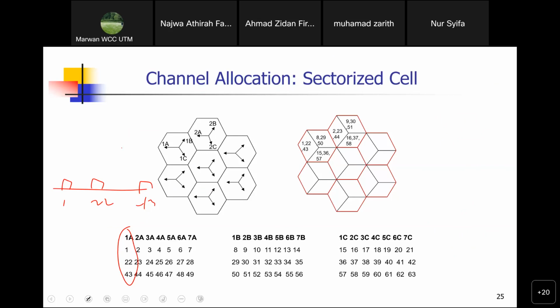If your local oscillator frequency is slightly changed, when you multiply it with the signal, your IF, your intermediate frequency, is going to be different, and that will also contribute to the adding of your adjacent channel into your filter. And another one, of course, is because of the environment.